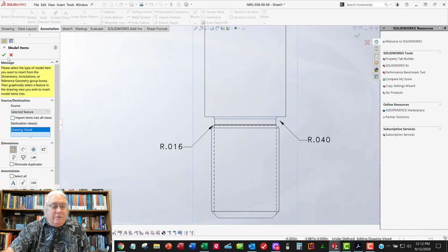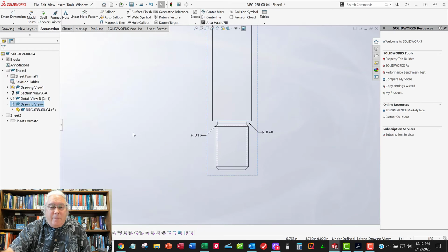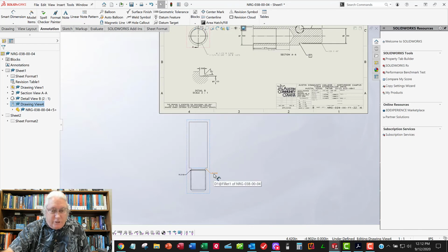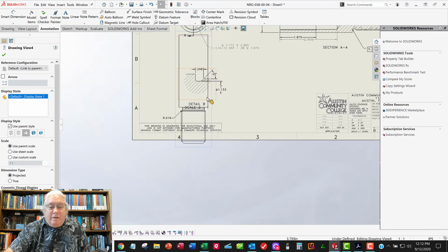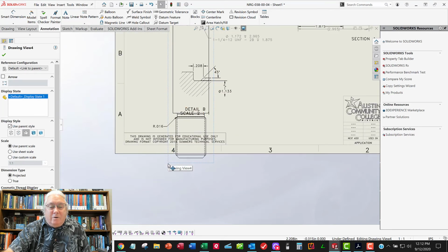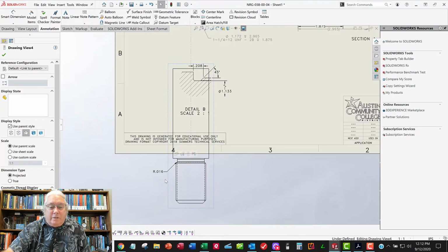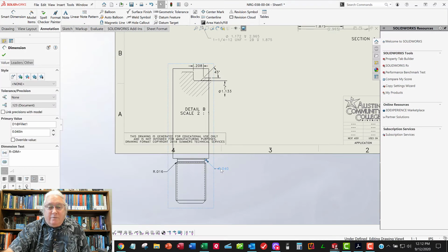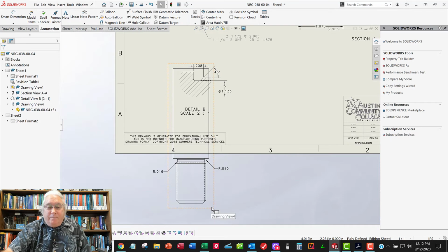I can't get those dimensions in the other view, and I can't even shift drag. You would think I'd be able to shift drag these to these other views, but unfortunately it doesn't let me do that. So we're going to have to just put some dumb dimensions in there because shift dragging doesn't work, unfortunately, because of that issue I just showed you on the model.